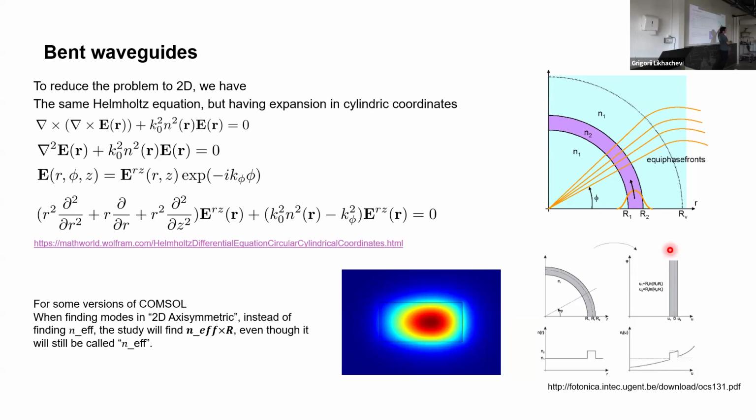If you experience more phase over the same angular distance, this intuitively corresponds to a higher refractive index. So you can think of it like this: the side away from the radius of curvature has effectively higher index, so the mode gets squeezed out.